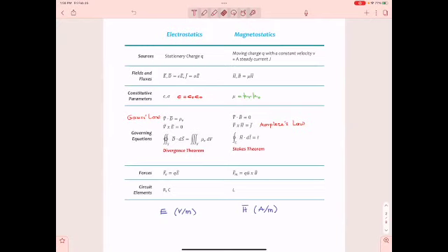For all of the dielectrics that we know, the most useful ones that we are working with, epsilon sub r varies from above 1 to about 15. So for example, for duroid it is 2.4 to 2.7. For quartz, glass rather, it's about 4. For silicon it is about 11.7. For gallium arsenide it is 12.4. And then maybe there is something else, graphene, whatever.